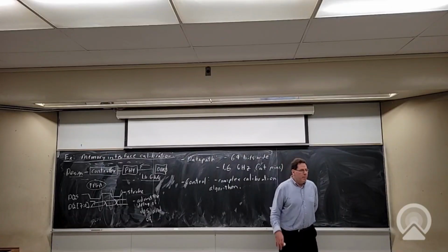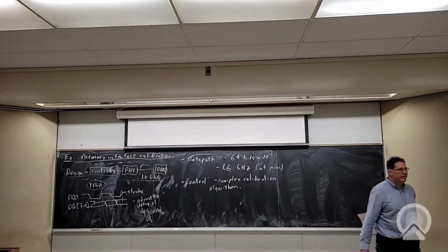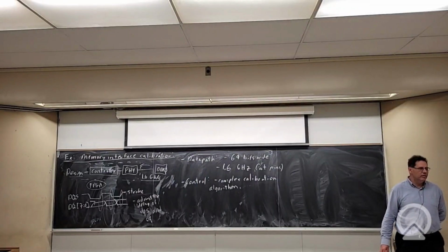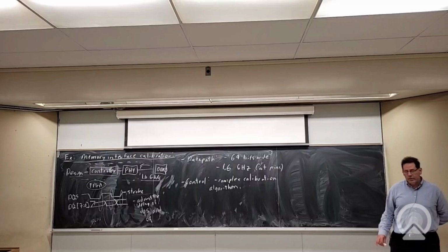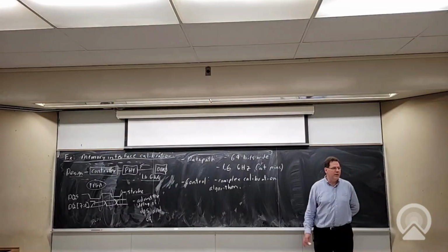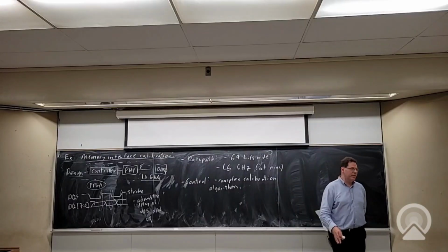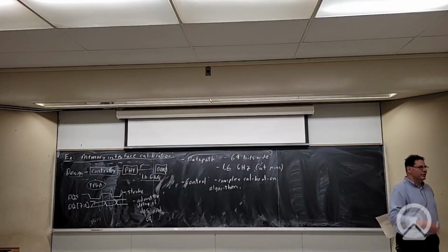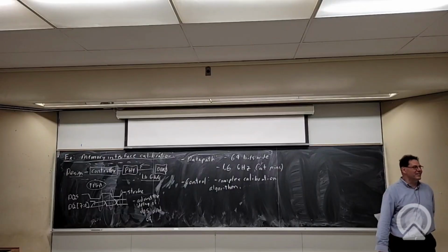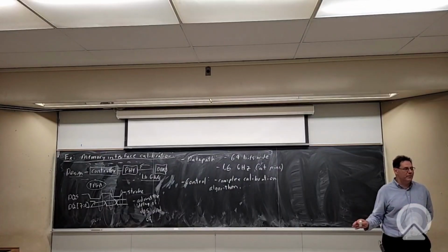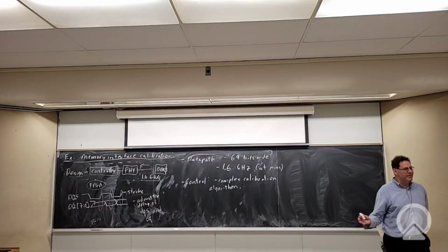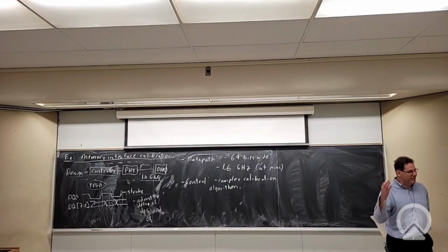No, but let's say you taped out your chip and it's an ASIC, so you can't adjust your algorithm on the spot. So ASICs have to build this algorithm in too. If you had an ASIC and you did not build a calibration algorithm, your ASIC does not work, your CEO is going to fire you. I promise you, because first of all, it's not going to work. You're not going to be able to talk to DDR, and they're going to say there's a problem with the calibration, and you're going to say I didn't use calibration, and they're going to fire you.